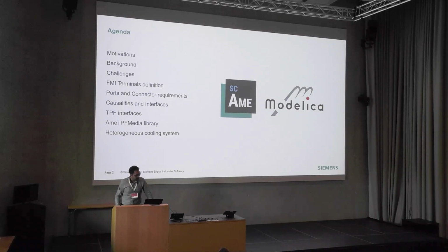And at the end of the presentation, we'll see how we developed specific interfaces to a Simcenter Amesim library for the two-phase flow, which is TPF, and a new library, AmeTpfMedialibrary, where we can simulate and use the different fluids from a database. And at the end, to validate the concept and the methodology that we will present, we have a use case, a heterogeneous cooling system, where we will use the different technologies that I will present.